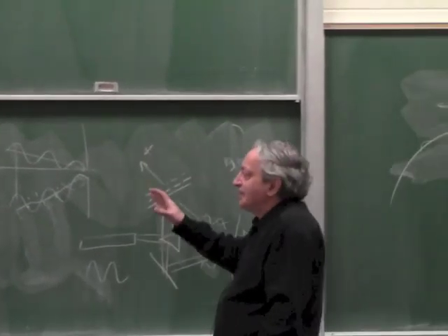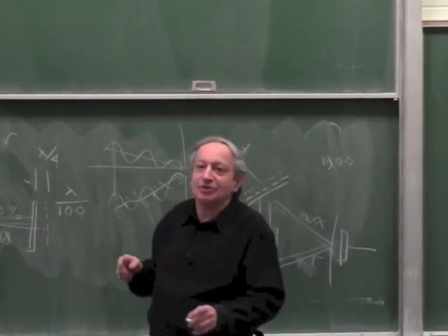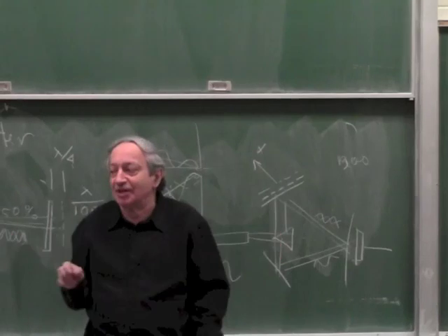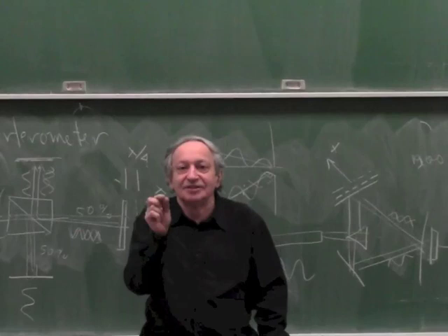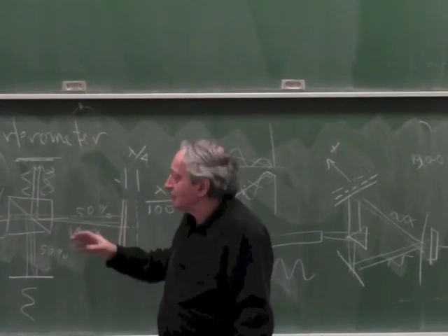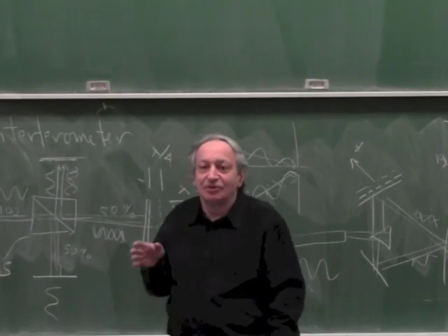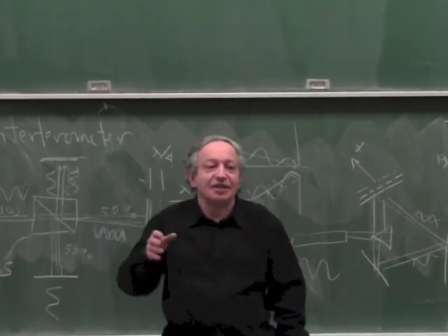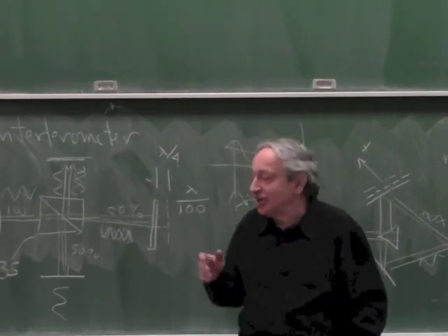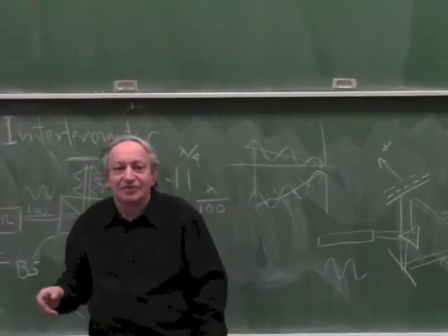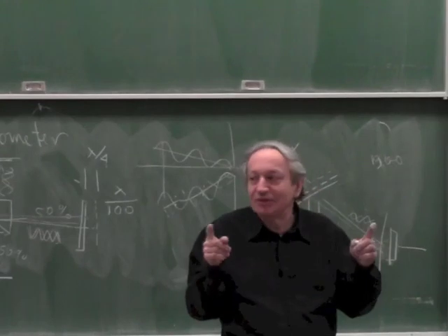So by using all these clever differential tricks, you can measure tilt, you can measure motion. So this is today the standard of accurate displacement measurements, especially when you need to measure over a big range, because a capacitive sensor is even more sensitive than this, but only works well, say, up to 1 millimeter. But this works well up to, say, a few meters. The limit to the accuracy, of course, is that it goes through air, and the air itself is not stable. Because if the speed of light in air changes, the readings will change. Now the air has moisture, has CO2, so it's constantly changing the speed of light.